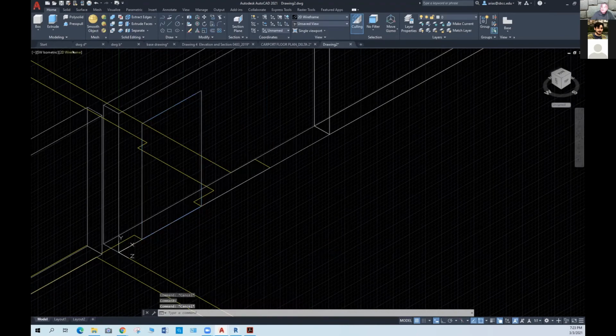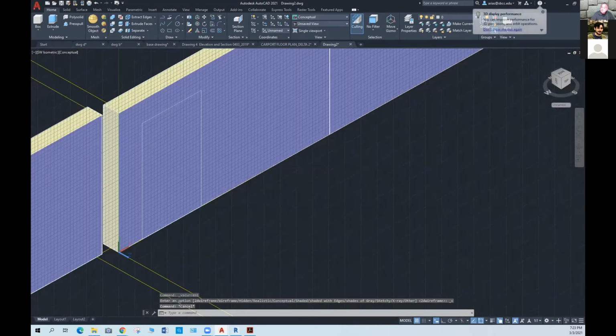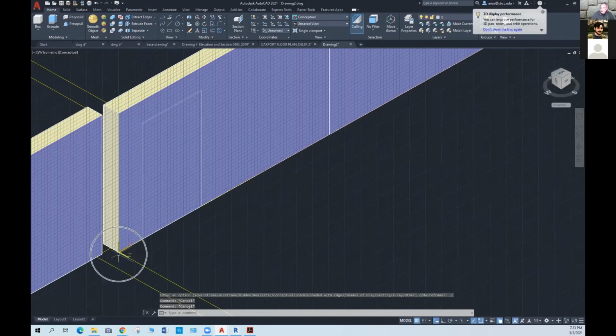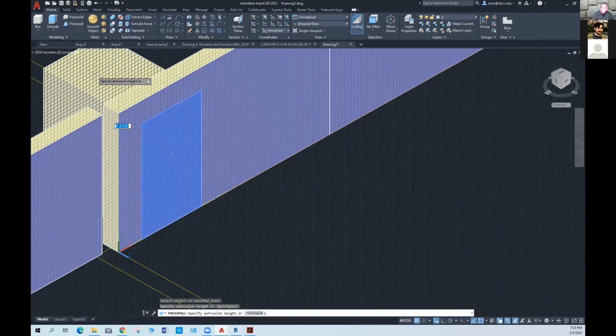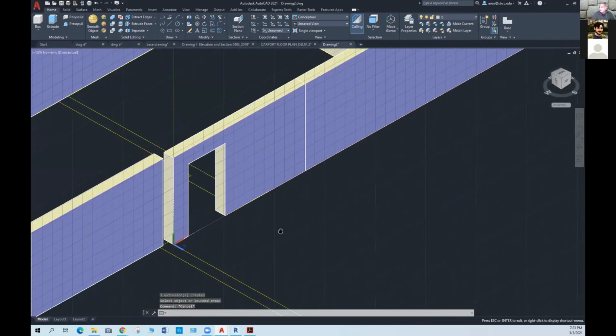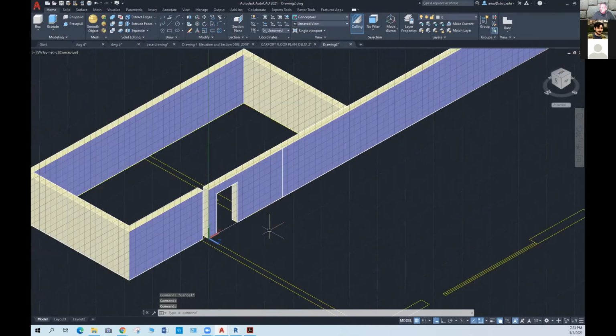Let's get back to conceptual. Now we know that we are on the 0 right there, so we could use press pull to create an opening. Select press pull, select the boundary, click and press. And now you have that door created. And so that's kind of what you can do that way. Now, there are other ways that we can create geometry like that.